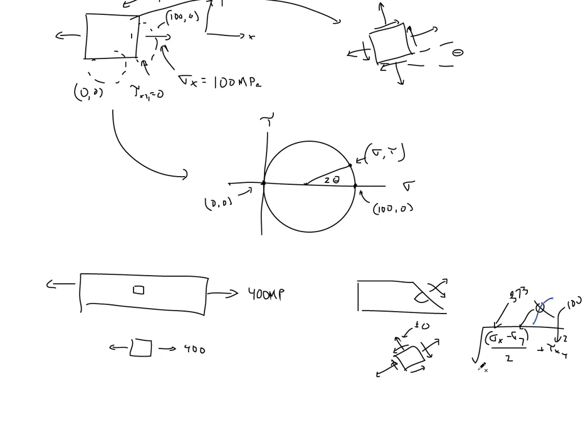You'd have to go through and calculate it for this particular rotation. But as this thing rotates, there is actually a stress on the other side right here, which is also associated with this shear that you calculated. So out here we have 373, 100, and over here on the other side of this element, you calculated this side, 373, 100, but this 100 is associated with another force over here, which is not 0. You can end up calculating it out.